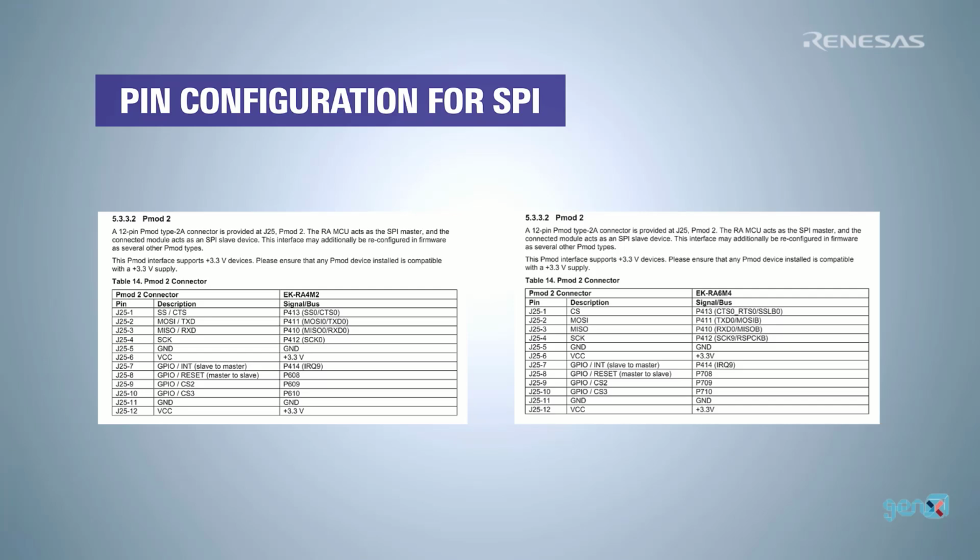The other possible configuration change needs to be with assigning the correct pins to the PMOD2 stack. Now, the PMOD2 port is hardwired to specific pins on the board. So, we need to make sure those pins are correctly assigned for this new board, since the default SDK is made based on the pin configuration of the RA4M2.